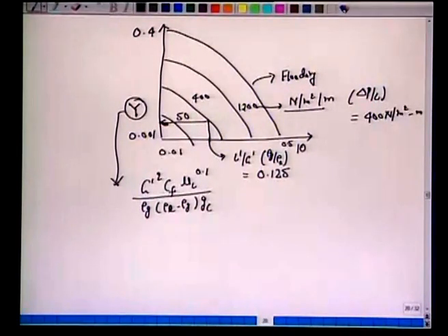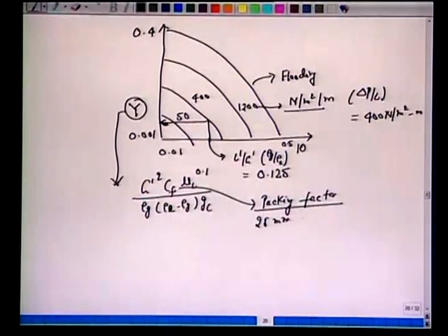Now you should also recall that the Cf is the packing factor, which means we are supposed to go back to the table we discussed a couple of lectures ago for this packing of 25 millimeter ceramic interlock saddle.